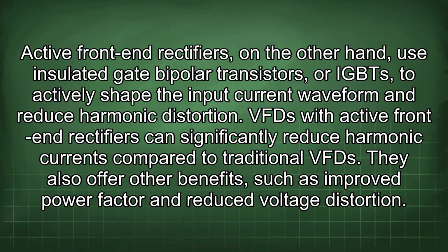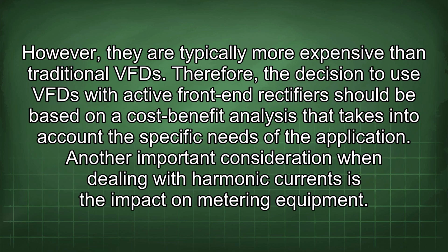VFD with active front-end rectifiers can significantly reduce harmonic currents compared to traditional VFD. They also offer other benefits, such as improved power factor and reduced voltage distortion. However, they are typically more expensive than traditional VFD. Therefore, the decision to use VFD with active front-end rectifiers should be based on a cost-benefit analysis that takes into account the specific needs of the application.